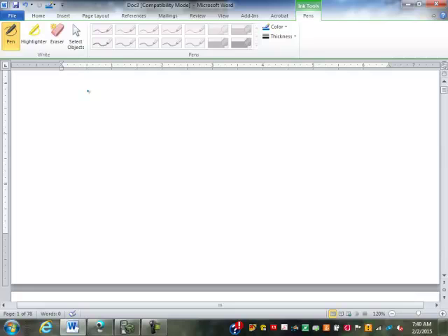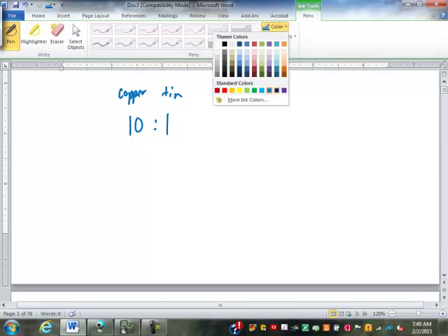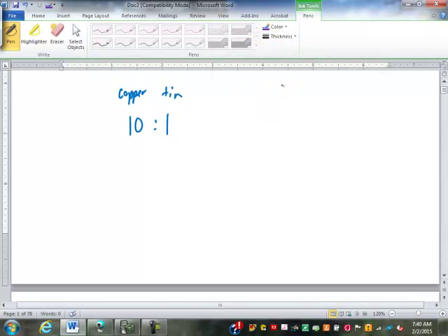Okay, I'm going to actually then jump up to number 78. Actually, the first number 78. No extra charge for the second one. Here we're looking at alloy ratios. So we're making bronze. It is a 10-to-1 copper to tin ratio. And it's asking, if I have 32 pounds of copper, how much tin would be used?